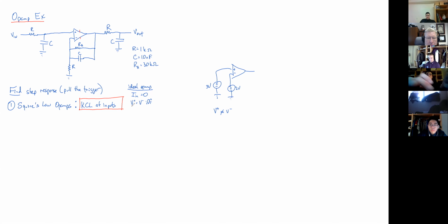Feedback loop? Feedback. You got to have negative feedback. Oh, Jonathan, I'm sorry. I missed you. All right. So as long as there's negative feedback. And again, what that negative feedback does is say that if it's not equal, the output will swing wildly in the direction to somehow go through this feedback loop and make these two equal.